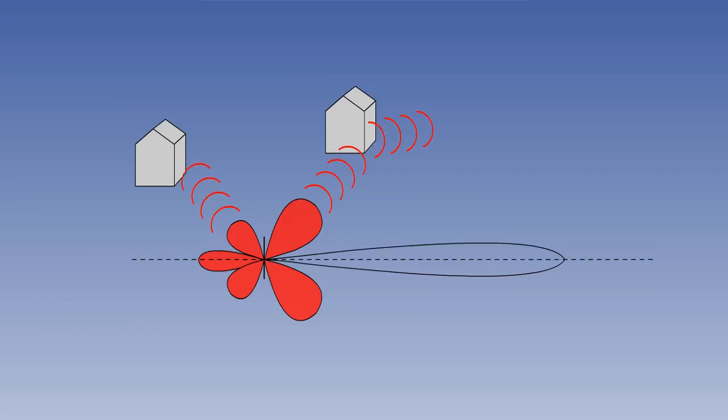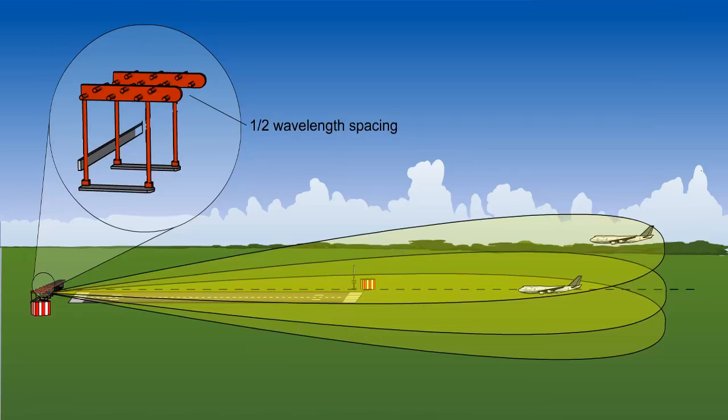However, directing a signal in this way produces side lobes, which transmit and receive unwanted signals, such as reflections from buildings. An application of the directed signal is the ILS. A narrow signal is produced from the localizer signal from an array of 16 or 24 antennae placed in line, with half-wavelength spacing, each antenna enhancing the signal of the other. However, side lobes are produced.